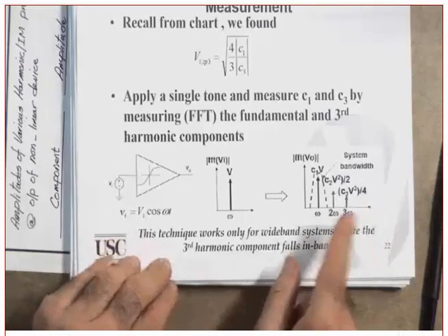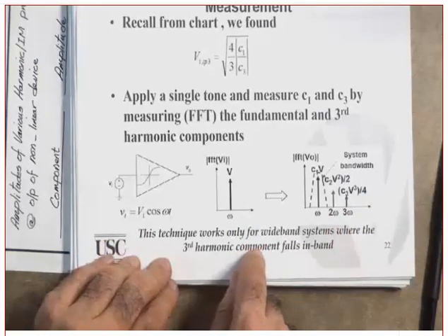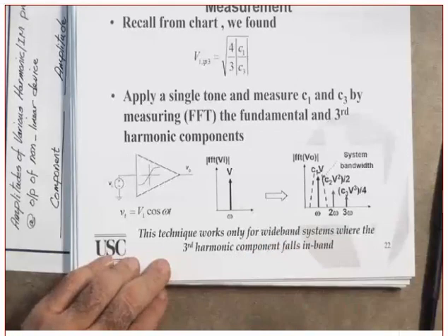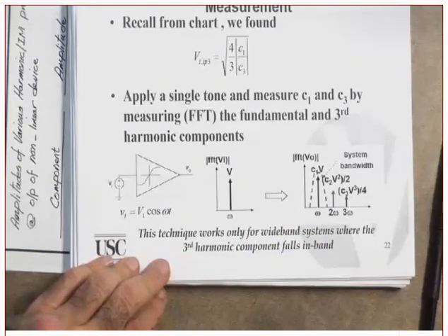But you have to remember one thing. This works only if your amplifier is wideband. Why? Because otherwise, the third harmonic component might be out of band. Are you following that? Which means the amplifier is going to attenuate it. Did you get this or not?